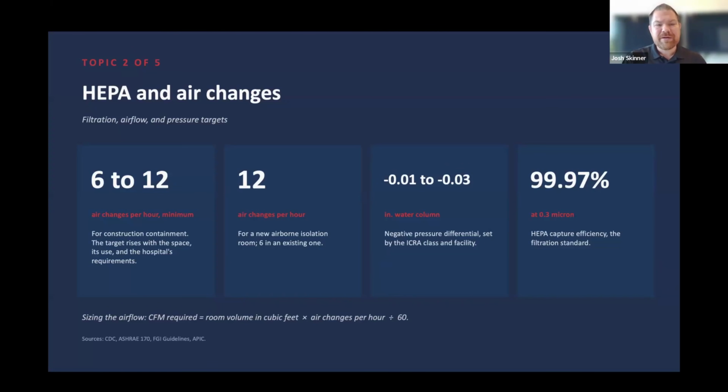If you have your team on a regular check schedule and using a checklist, that's the best way to ensure that every machine you have is never getting clogged up. And with that checklist schedule, you're doing a visual inspection. You're visually inspecting the pre-filters. Does this need to be changed? You're visually inspecting the HEPA. Is there damage to the HEPA medium? Two easy ways to say, I might have changed this HEPA a month ago, but it's been damaged. And if it's damaged, it's letting stuff through it shouldn't have let through.